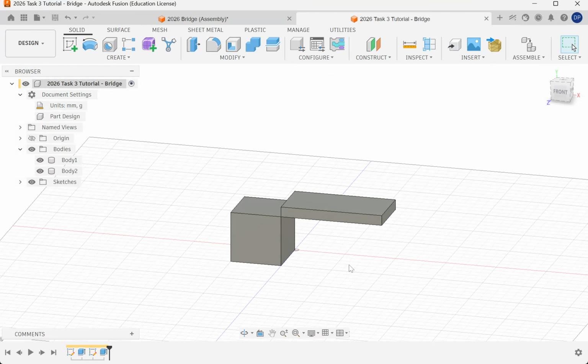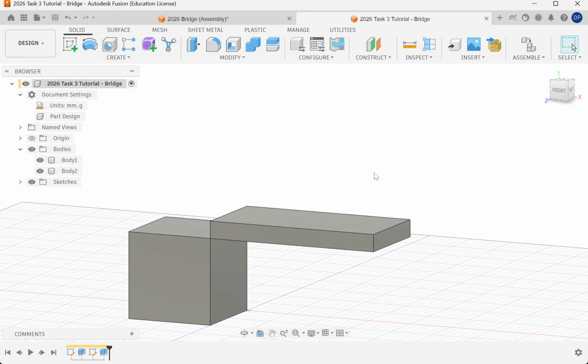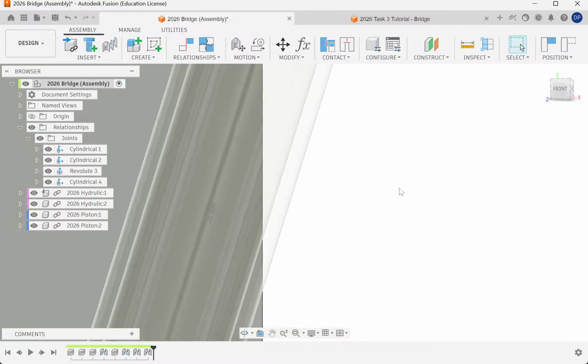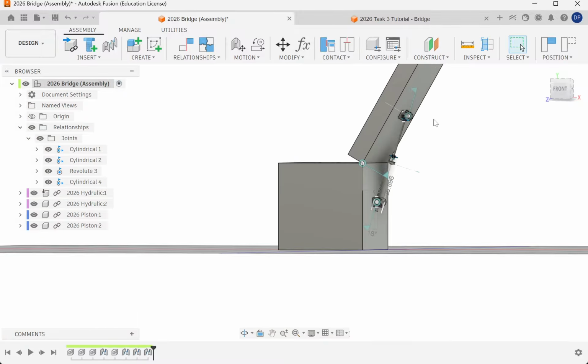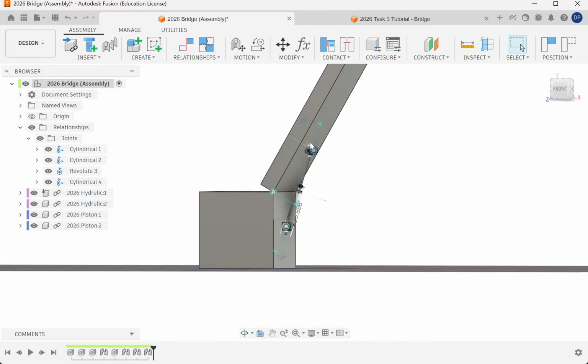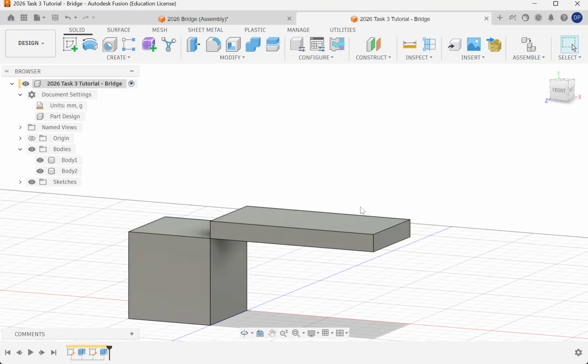So for this, I'm going to pick the location of these hooks. If you've done your sketches, you'd have a rough location where your hooks will be. And when we get our plastic syringes in from Amazon, we'll measure them and look at our sketches, and we'll get a rough location. I guessed here that the location of these syringes where they would match in our design would be somewhere here, which is not exactly the middle, but roughly there. And this one's roughly in the middle. So I'm just guessing the location for this.